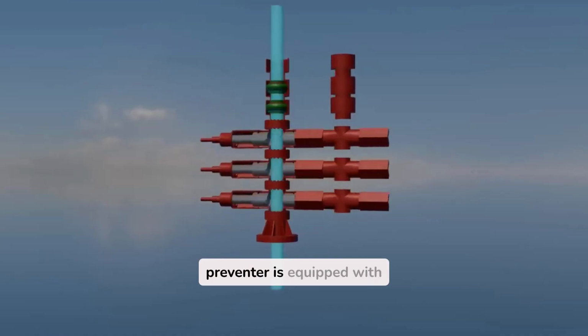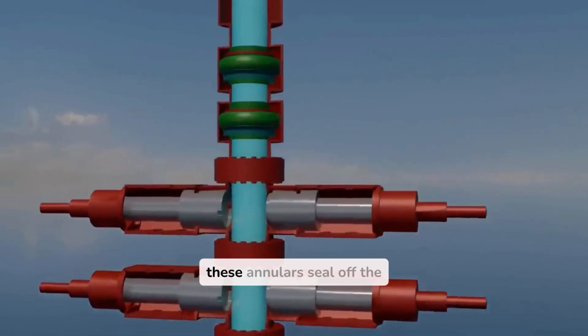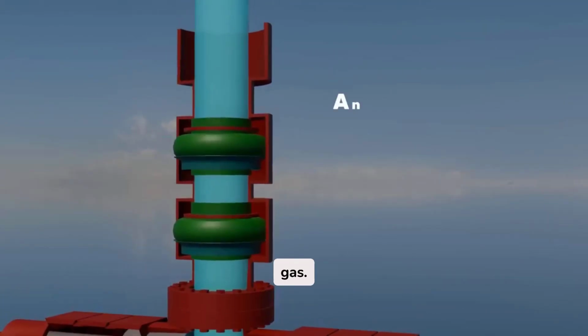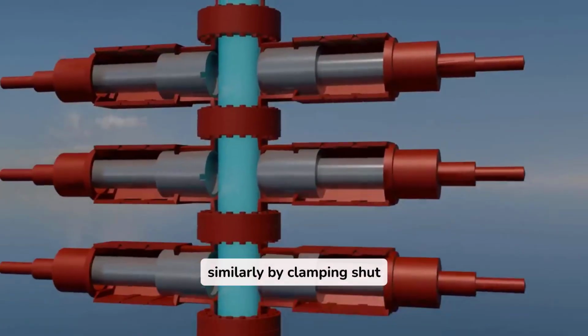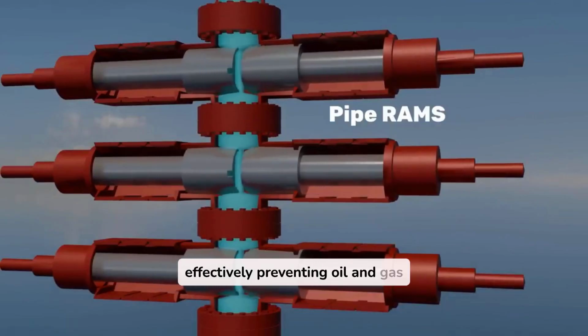The blowout preventer is equipped with annulars, which are shaped like large donuts. When tightened, these annulars seal off the well and block the upward flow of oil and gas. In addition to these, pipe rams are also used. They function similarly by clamping shut the pipeline when the pressure becomes too high, effectively preventing oil and gas from